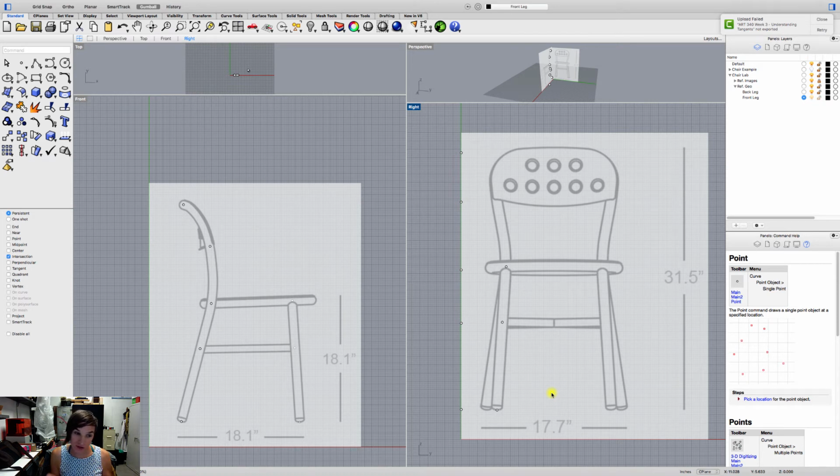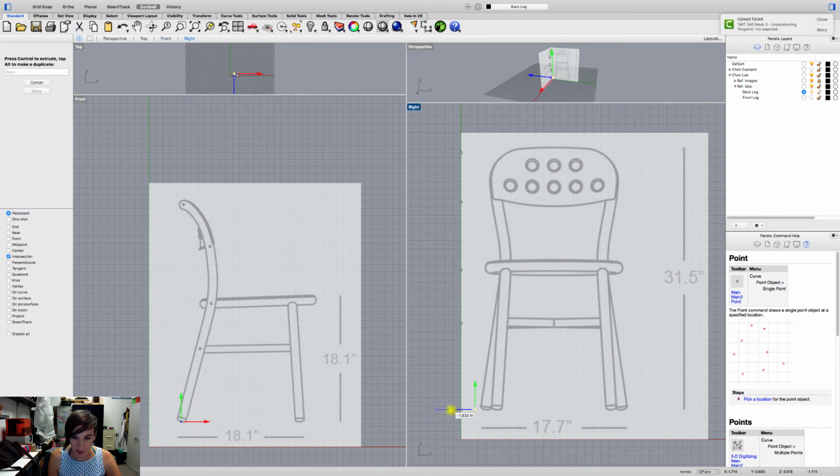And when it comes to design and manufacturing of objects, we want them to be even unless your design specifically calls for them to be different or asymmetrical or something like that. But our goal here, we're going to adhere to the design of this chair for now and move forward with a symmetric chair. So back to the back leg, I'm going to turn those points off, and then I can start moving my points for my back leg.